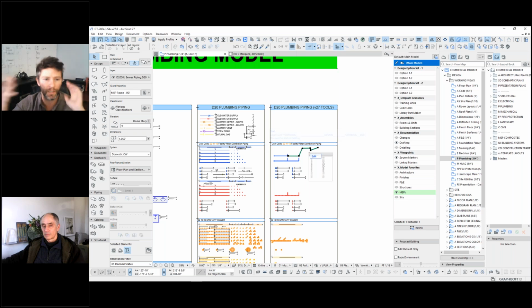So it's kind of like we're in this weird timing between version 26 and 27, which has now been released, and the 27 MEP tools are not really up to par for producing detailed modeling if you want quantity takeoffs and material listings. But the version 26 stuff didn't always have the perfect types of connections anyway. So hopefully the tools will get better. I think Graphisoft has some plans for where the tools are going to go. But for the basic user who just wants routing without caring about the fittings, the tools are probably better now, or at least easier to use.